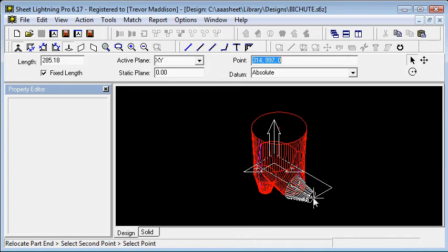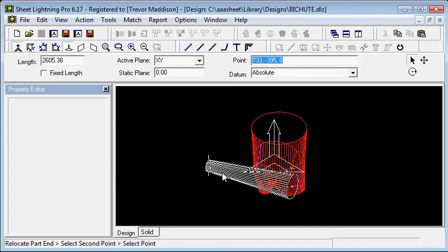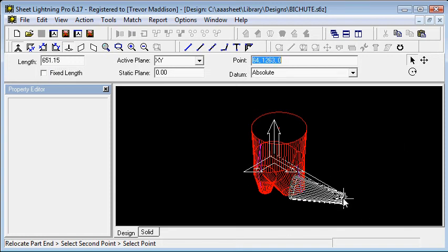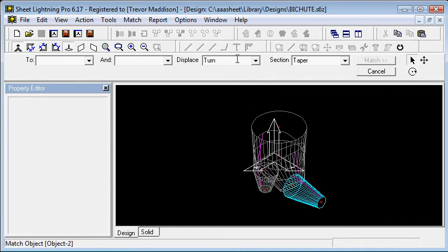So let's select on that, and now the cursor movement is operating much like when we first create a new part, and this part is following it. It's locked in terms of its length. We can unlock it and then it will stretch out that part. Let's align it to the axis as a modification. Let's give it a length of say 500, and then we just drop it in place so it's horizontal.